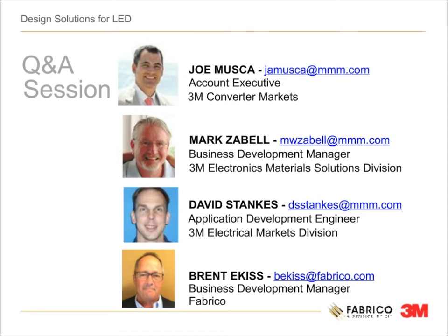Our first question: when an LED light fails using a TIM, is there a possibility of a fire? I can take that, Steve. Most of these materials, just about all of them, meet UL vertical burn 94V0. So they are self-extinguishing. They would not contribute to a fire.